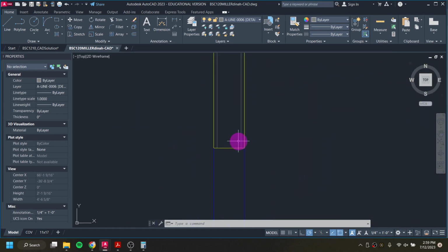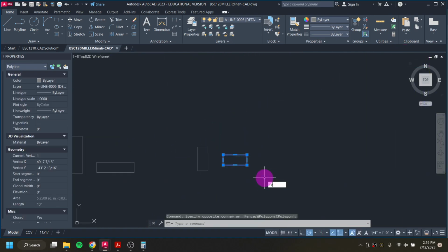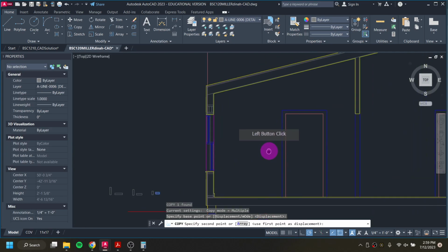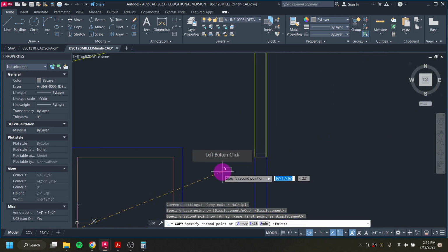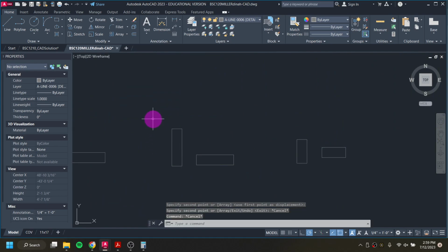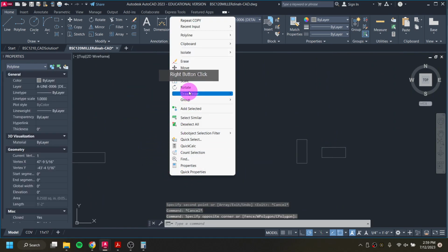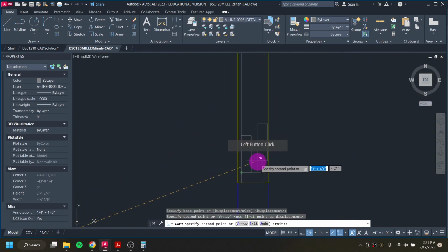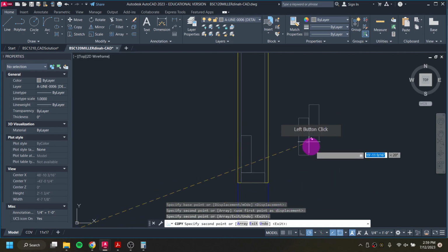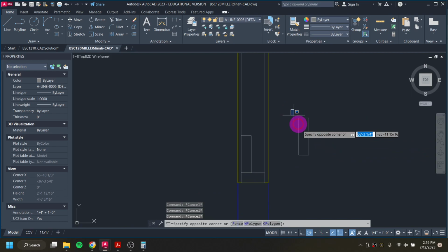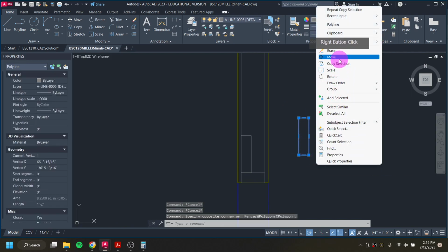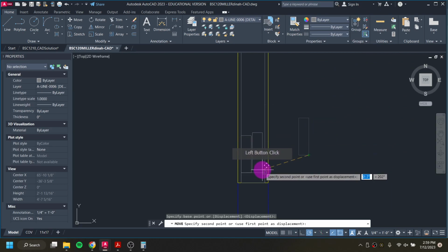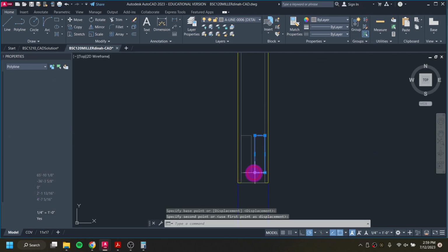With our header above this door here, this is going to be composed of, I meant to do copy, enter. It's going to be a 2x4 sitting in between, and then a 2x6. So right click, copy, grab it by this corner, put it in this corner. I can also put another one over here to the side and then hit escape, highlight it, right click, move to move this one into place rather than keep getting them from that side.